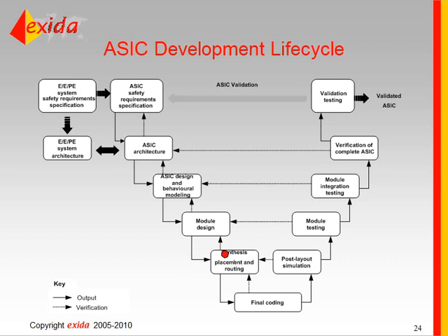The synthesis placement routing step takes the module design and converts it into a gate level design. So the module design is done using a hardware description language such as VHDL or Verilog. And then the final coding is done after the synthesis placement and routing. Some changes might be needed. Then post-layout simulation. After the placement and routing has been done, you'll do some timing analysis to make sure that the timing of the circuit is acceptable.